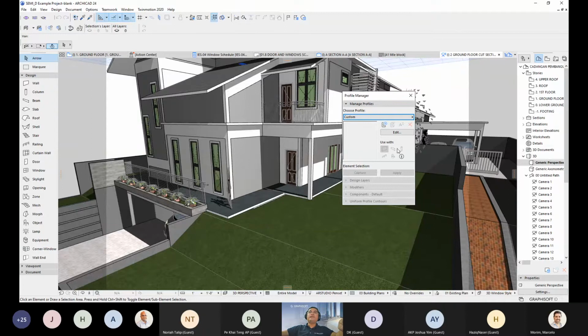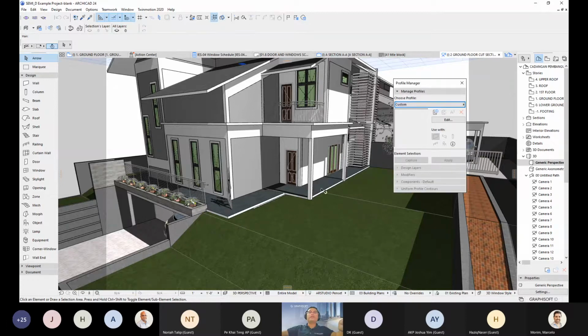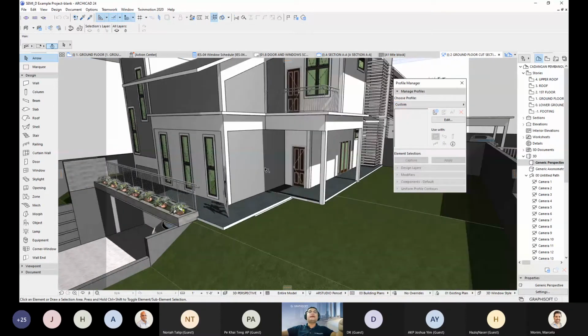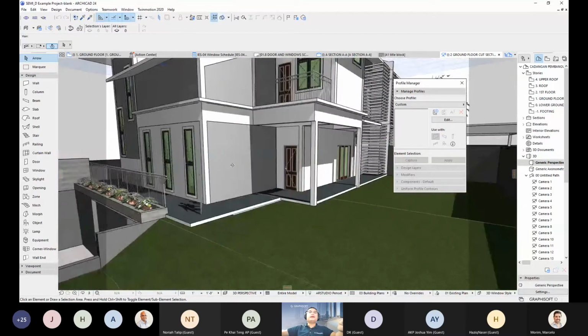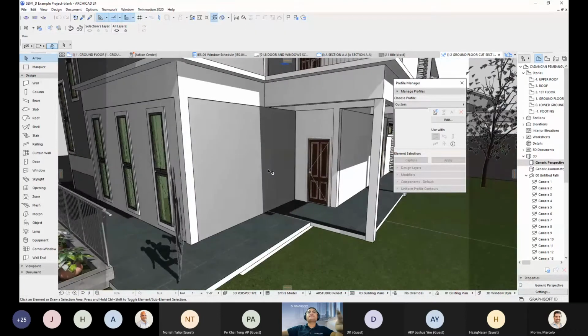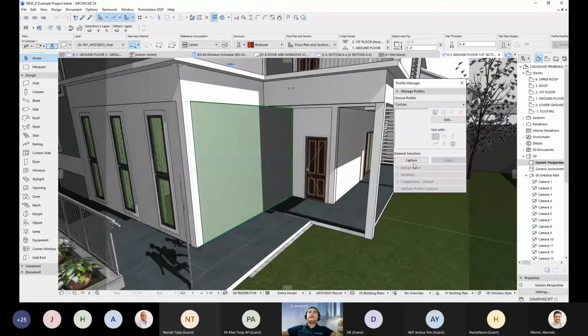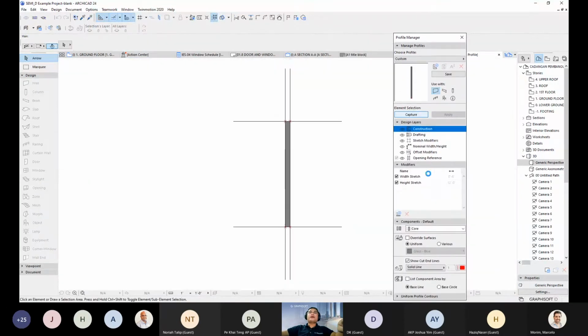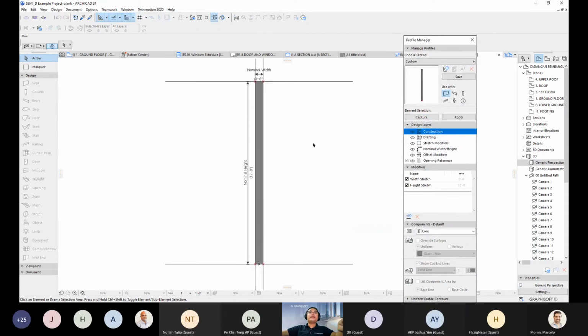You can save it as your own profile, and you can apply this to any specific element in ArchiCAD like wall, beam, even column, railing, object. Okay, I will show you one example here. Now I want to create something like a groove wall, maybe in this wall. So I can just select this wall first, and I can capture. After I capture, it will automatically capture that specific wall in the profile manager.